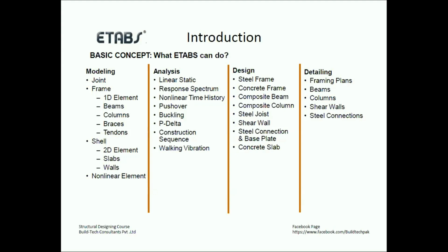You are even able to see the shear force diagrams and bending moment diagrams for all of your beams and columns in just one click. If there are like 1,000 members, you can see the shear force and bending moment diagram for all those 1,000 members in one click. So next we will move toward the design phase, once the analysis phase is completed and you get the response of your structure.